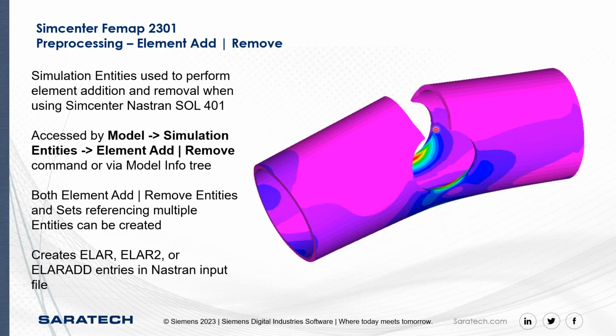But before, you could specify a row of elements here to say, for example, once the mechanical strain exceeds a certain amount in these elements, I would like them to be removed. As we load up this part, that mechanical strain would build up, and you would see this unzipping effect, and those elements would be removed, and then you would see the picture that you show here once those elements are removed.